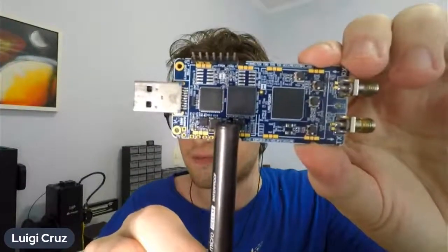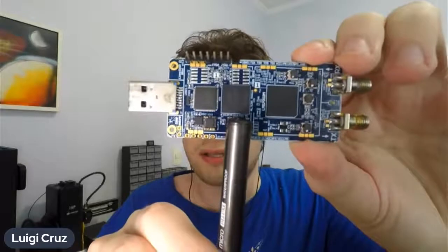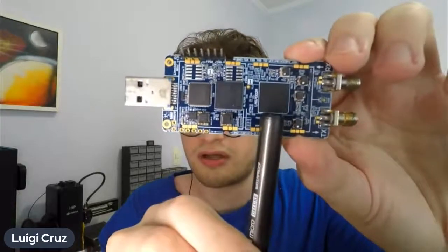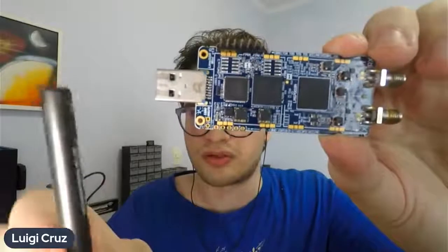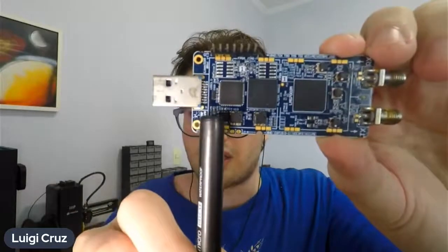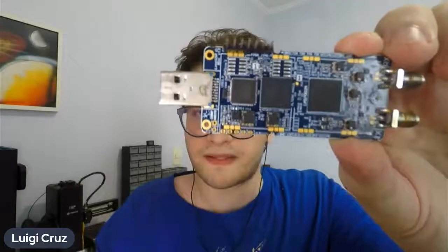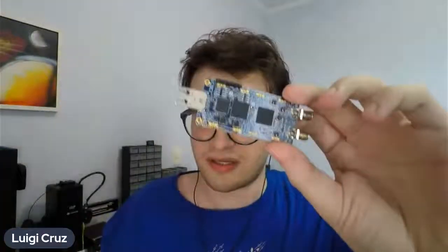This is the analog front end that receives the signal itself. It will digitize the signal and pass it to the FPGA, the MAX 10 here. And the MAX 10 will take the IQ samples from the analog input and send them to the computer using the FTDI here, using USB. So this is the tiny little radio that can output 30 megahertz of bandwidth and goes from 10 megahertz to 3.7 gigahertz. It's a bit more than the RTL-SDR.